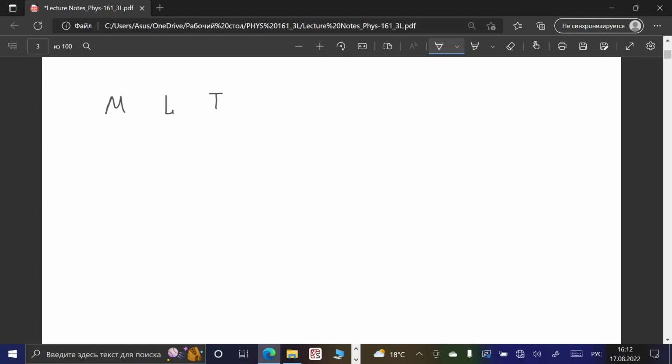So if the temperature is different, the length will also be different. That means you need to keep all the same conditions, which is not so trivial to realize. And then you calibrate your devices with some unit which is not constant, meaning your different devices will measure with different accuracy and will introduce systematic errors to measurements.